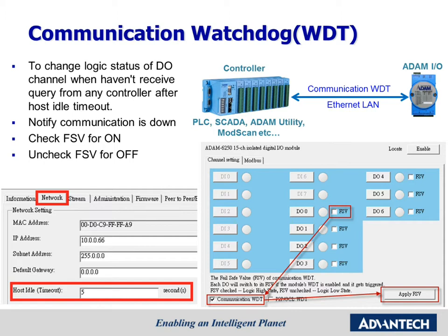The logic status of DO channel will become high when FSV is checked. Otherwise, the logic status of DO channel will change to low. Besides, please remember the host idle time and FSV setting for each channel must be defined before using WDT